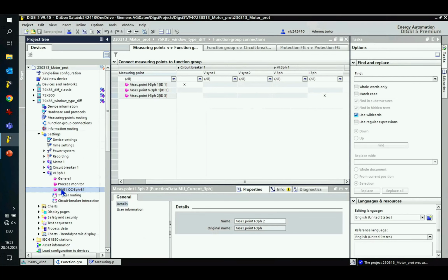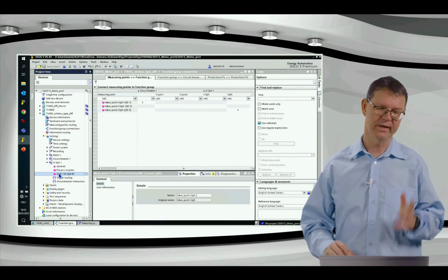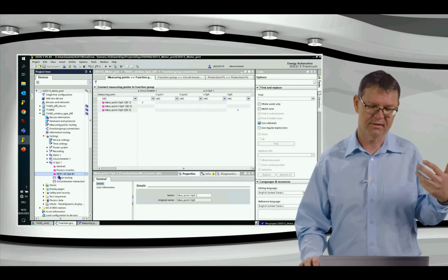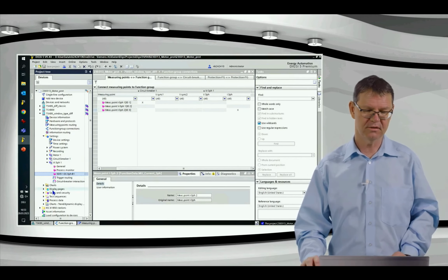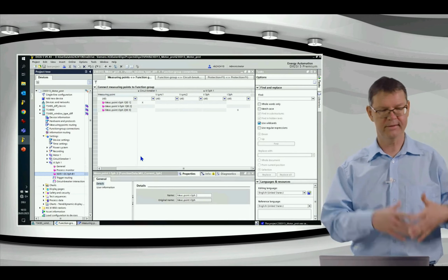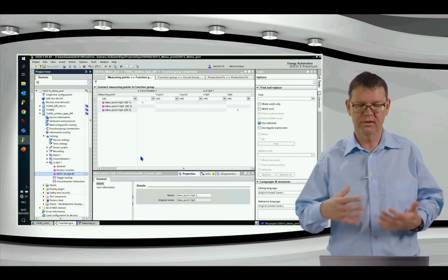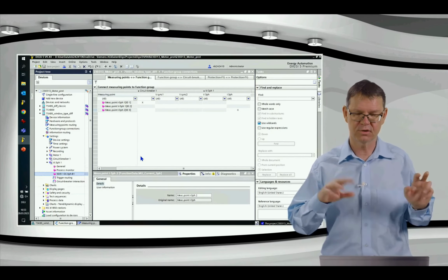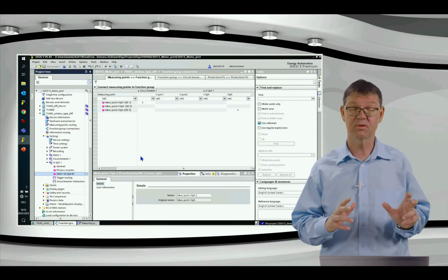It is yes, because for each current transformer we just need to add the proper hardware, and then we add here the functions, and then I have individually customized functions for each motor. And I can add more than 2 motor protection functions or schemes inside, 3, 4, 5. The exact limit I need to check, but I think at least 5 is possible.